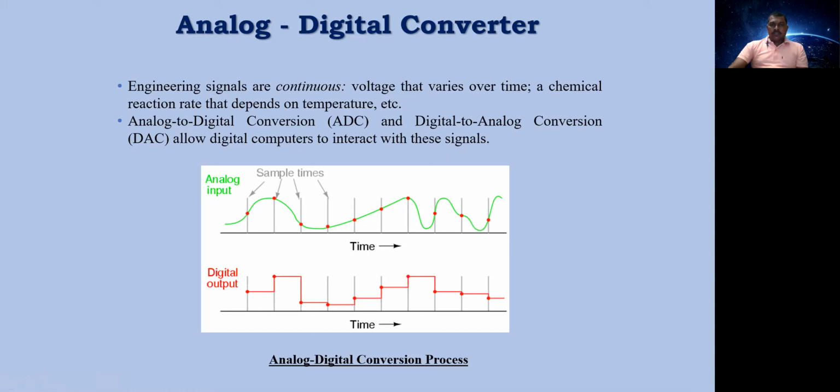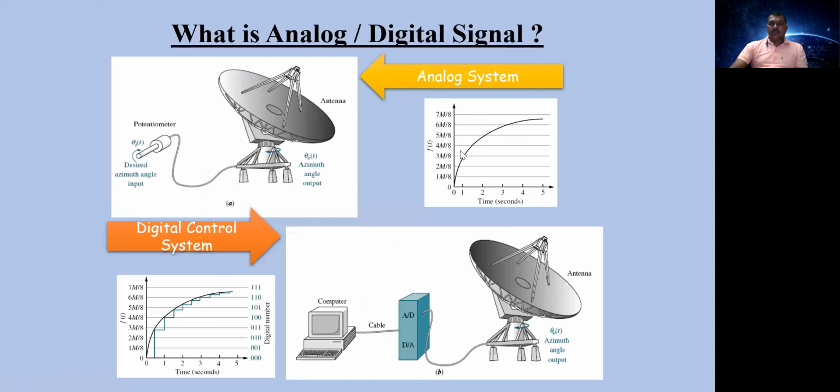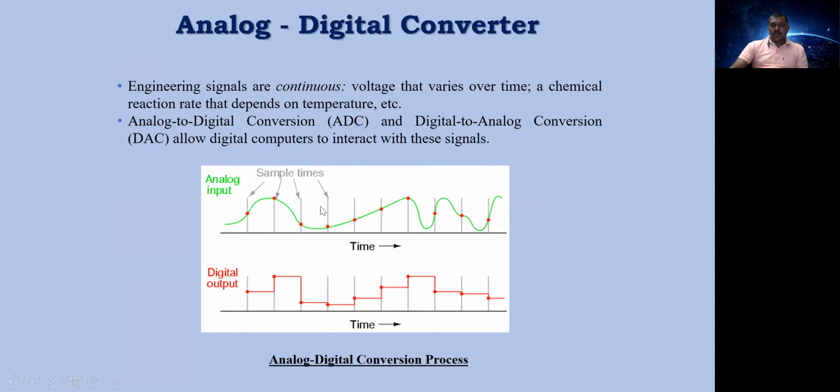Now, the signal which is here is to be converted into digital, right? As you can see, we are missing some of the points. Here we have sampled and quantized it, but if you look, this lands in 110 and 111. It does not reach this point, that is 111, right? So we are not able to convert this portion of the signal into digital. So how to convert all these points?